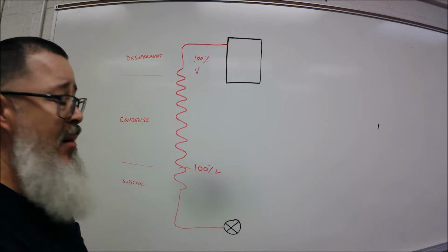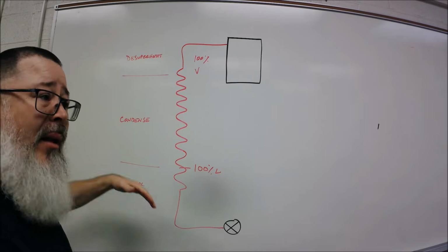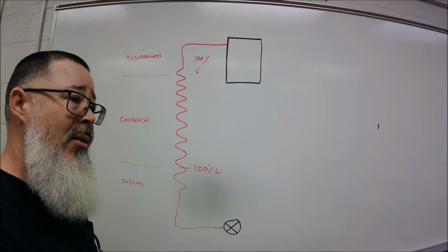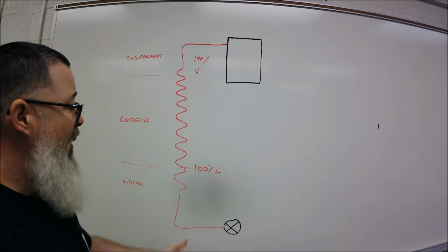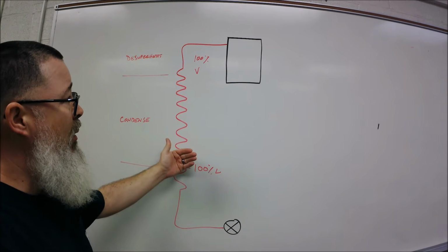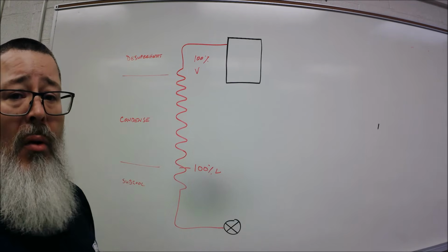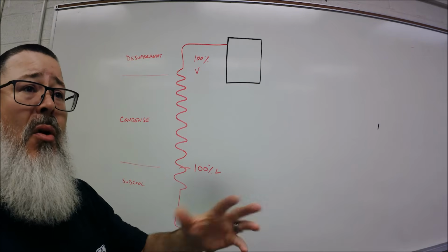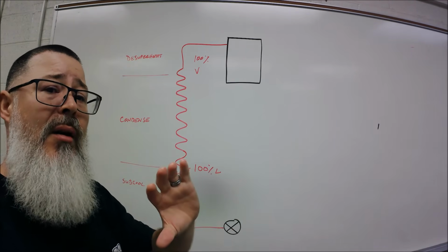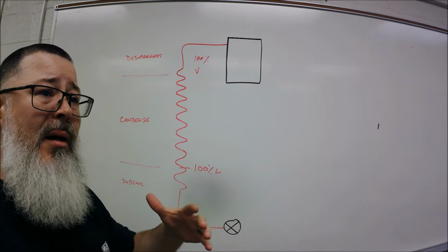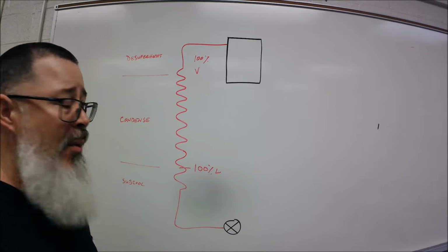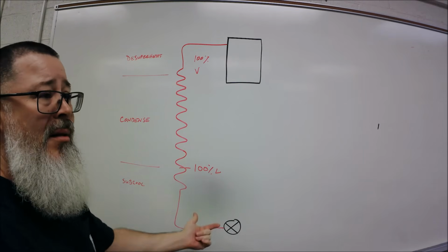And that's, right, since we're talking about subcooling now, and that's really the focus that I try to put on this. Once we make 100% liquid, we are no longer concerned. I mean, the saturation chart, the pressure temperature chart, that saturation point is a reference point now, because we're going to calculate subcooling.